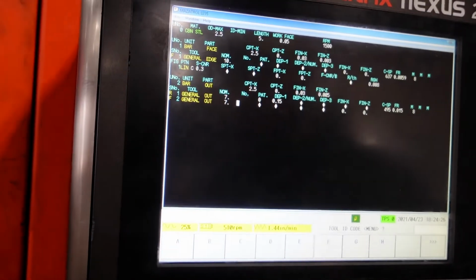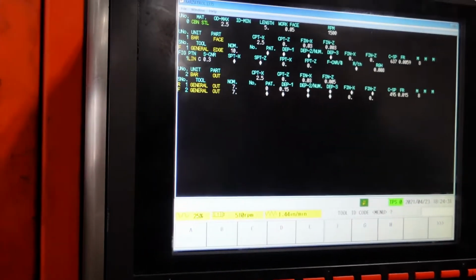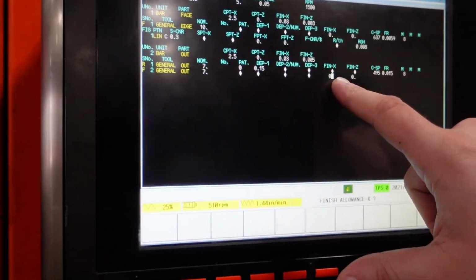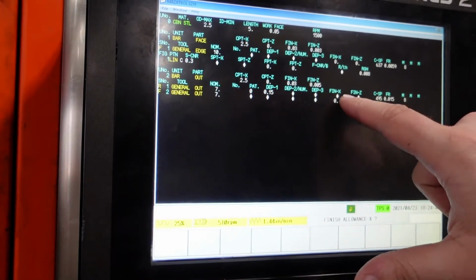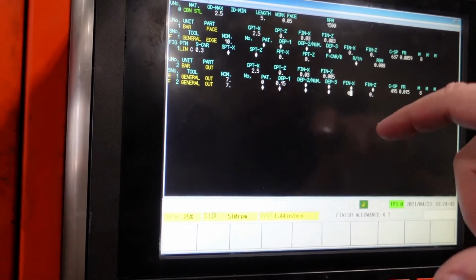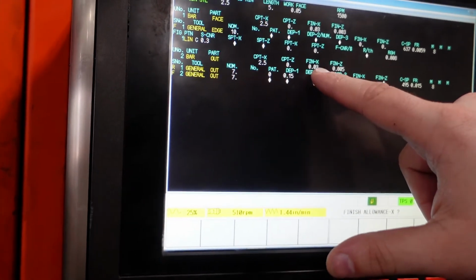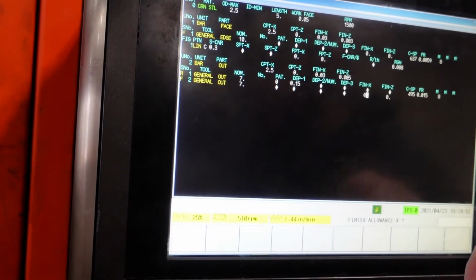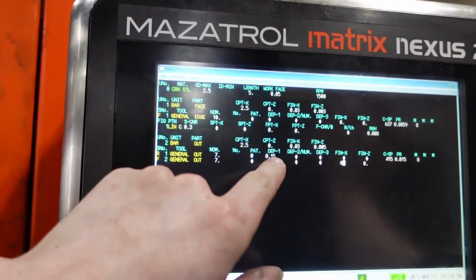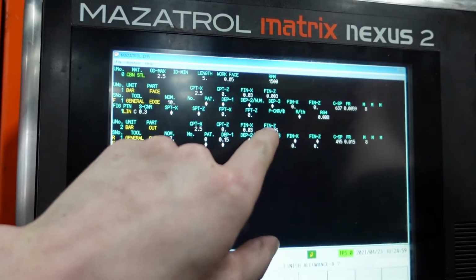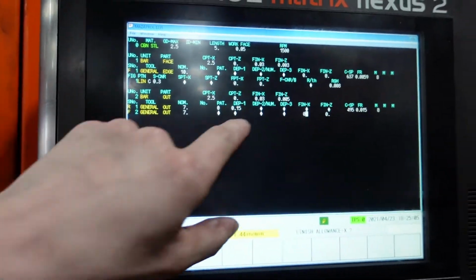Now, we're using the same tool to finish with that we're roughing with, because we really don't care. Same sort of deal. We're not going to have any finish allowance in X for our finish tool because we want this to be two sides. If you make this 30 thou, it'll be 30 thou above what you tell it to later. It is going to rough it 30 thou above where you want it to be, and then it will do its finish pass at what you say it's supposed to be when we get down here. If you rough it down here to 2 inches and you leave 30 thou, this will be 2 inch 30 thou. The finish is going to take it to 2 inches.